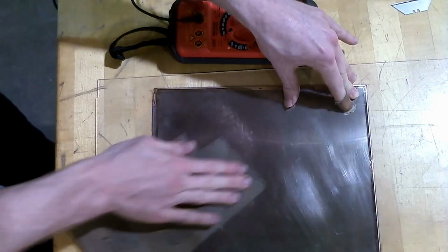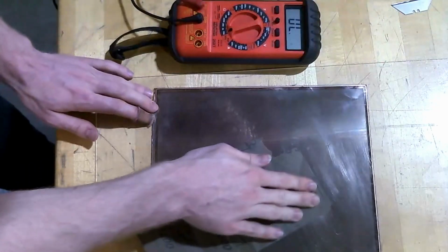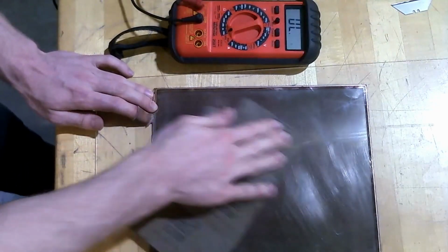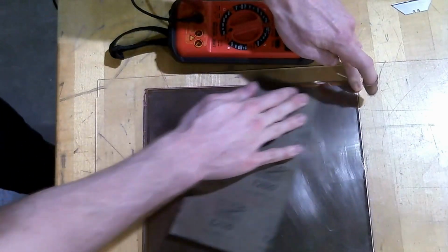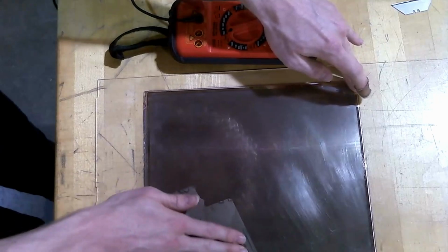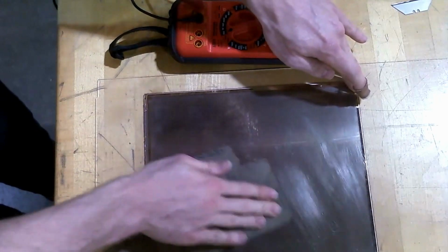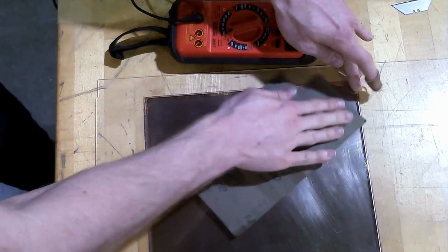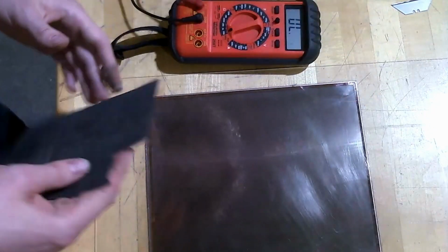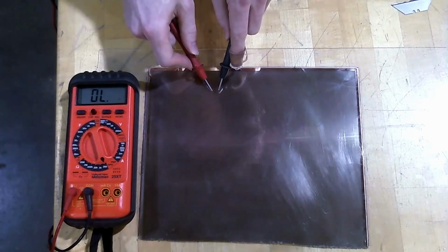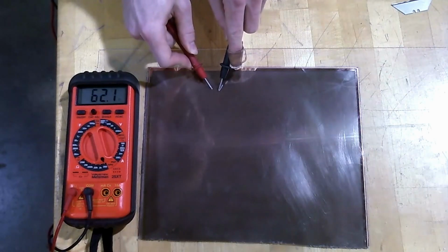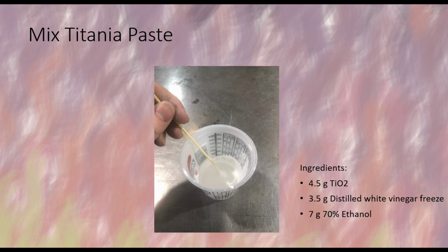And after we've removed this layer, we are going to do a quick check of the resistance of this conductive glass. If you look at the meter during this, you'll see that it fluctuates and doesn't sit on a value. It's because it's not a perfect removal, but we'll see it sits somewhere around 50 or 60 ohms, which is excellent.